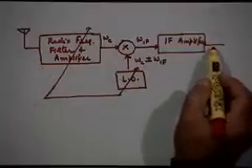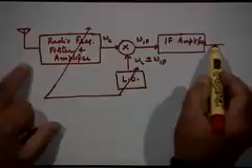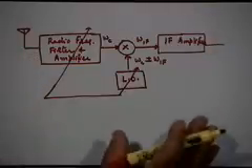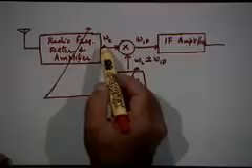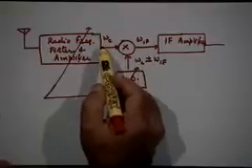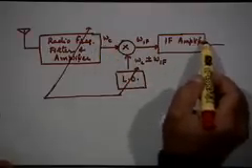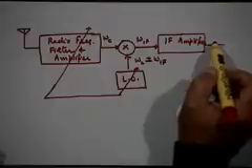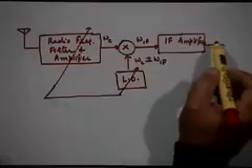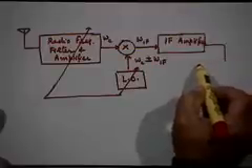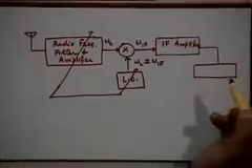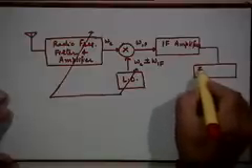Let me complete, the nature of the signal here and the signal that was coming in are identical. All you have done is translated the modulated signal from omega c to omega IF, right. So you again get an amplitude modulated signal here, except that the carrier frequency is no longer omega c, but the carrier frequency is omega IF. So after this you have to do the demodulation, for which you can use whatever you would like to use. Typically in this kind of application, it is an envelope detector